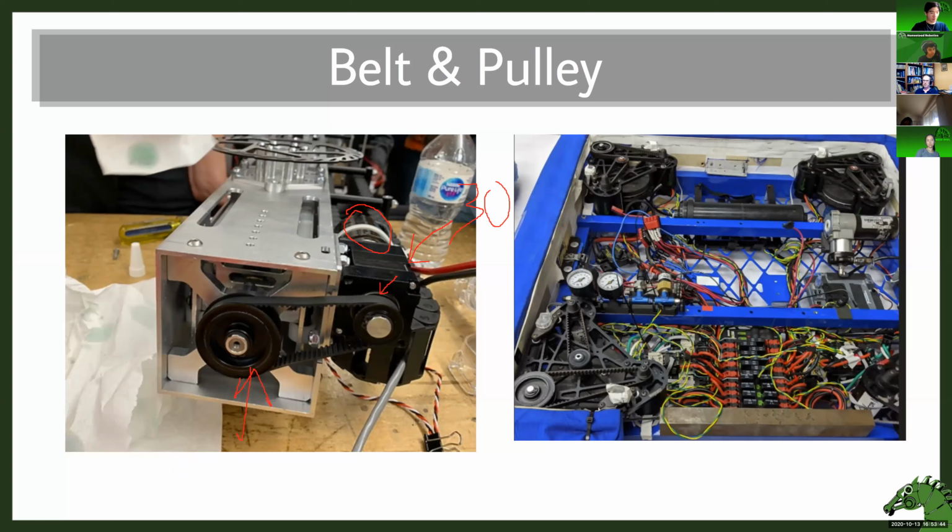And the good part about this is even if it's a small ratio of like 1.5, this 1.5 ratio is multiplied by 30. So your 30 gear ratio through this first reduction is multiplied by 1.5, and you end up getting a ratio of 45 for not too much extra work. It's a lot of benefits here for packaging and also ratio reduction.